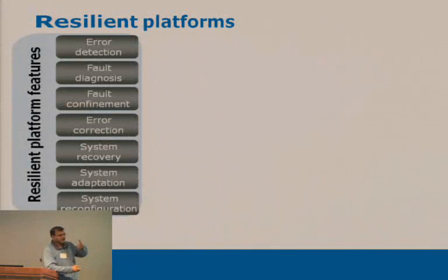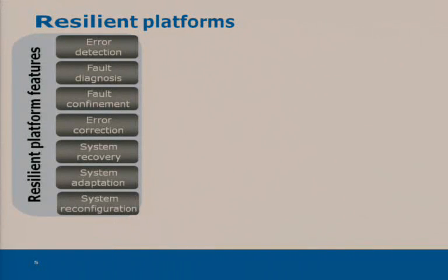So resiliency or error detection correction has been widely used in servers, as we know, high-end enterprise-class servers to improve reliability, soft errors or infrequent errors. There's some work recently going on to really apply that to improve energy efficiency and performance by basically pushing the voltages and frequencies beyond the point where some errors occur due to timing failures, and then having mechanisms for detecting them and correcting for them, so that as long as those errors are infrequent enough and the recovery overheads are low enough, you can maybe get some benefits in energy efficiency and performance by pushing the envelopes of voltage and frequency.